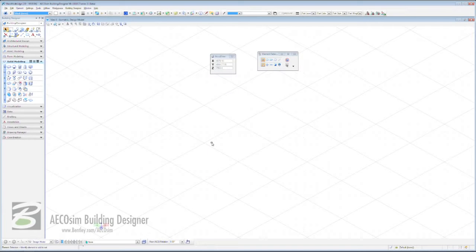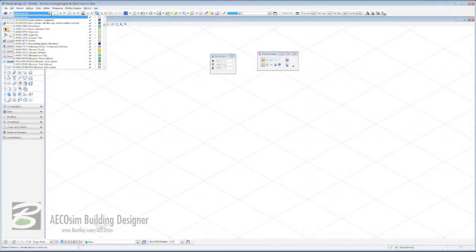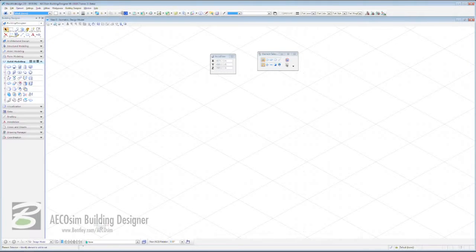The other components of Building Designer include standard pull-down menus, including this one here, Building Designer, which allows you to load by default architectural or space planning, all the structural abilities, mechanical or the electrical building information modeling toolsets and analysis. We have standard icons across the top, including generic attribute ones, including our EDS across the top here, management ones in our primary toolbar from models and references to level manager, level display, project explorer to AccuDraw. We can customize these however we want by simply right-clicking on them and turning off any of the ones that we don't need.